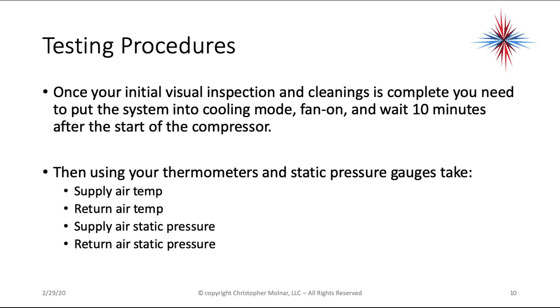Once your initial visual inspection and cleaning is complete, you need to put the system to cooling mode, fan on, and wait 10 minutes after the start of the compressor. Then using your thermometers and static pressure gauges, take supply air temp, return air temp, supply air static pressure, return air static pressure. And by the way, supply air temp and return air temp, you want both the dry bulb and the wet bulb.